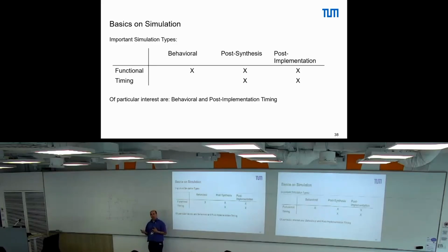So the timing is not one fixed value, but it's usually somewhere in a range. What you do in practice to cover this is that you have a maximum and a minimum delay. So we may have here T clock max and a T clock min, right?